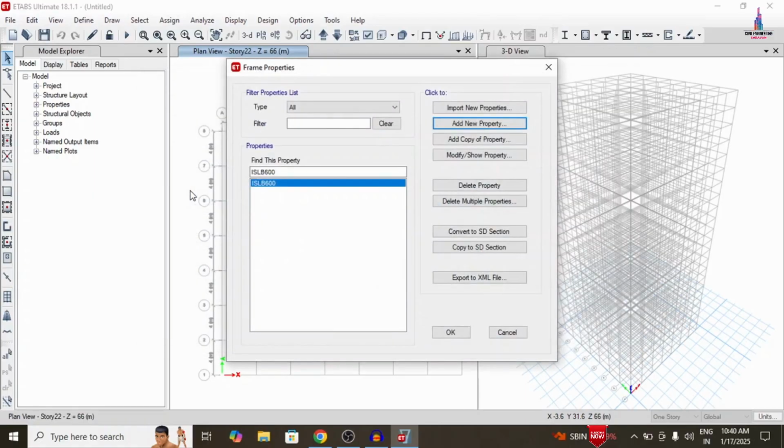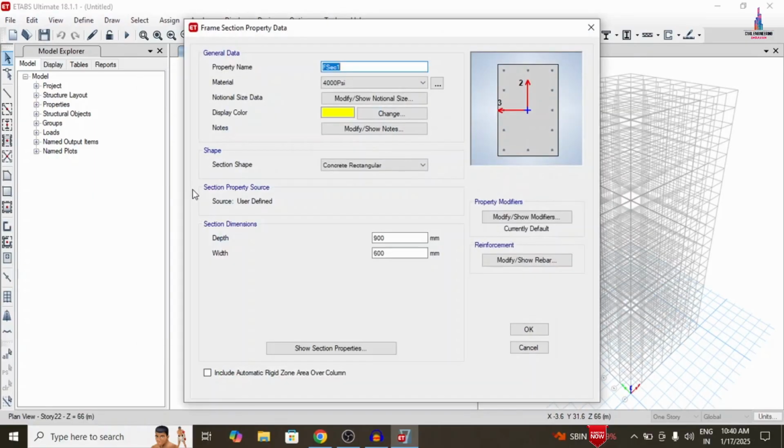Click and select your concrete design. So here in this case for the column, I am assuming dimensions of 0.69 cross 0.69 for the column section, and the material we have to select is M30 grade. Now we have to enter the dimensions of the column for this building structural model, which is equal to 690 into 690. Again we will select the show selected property.